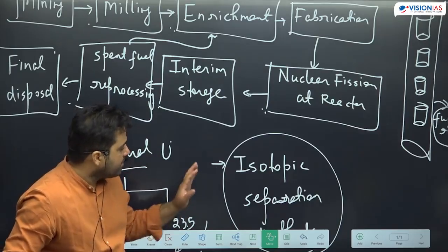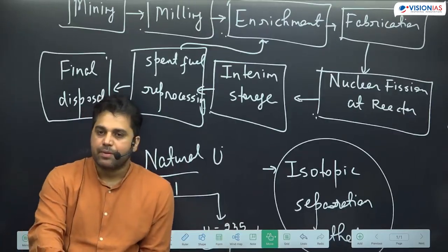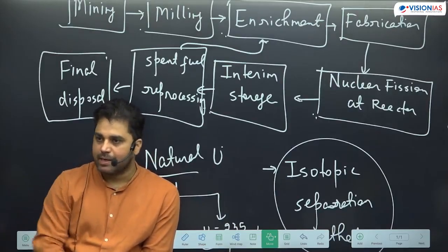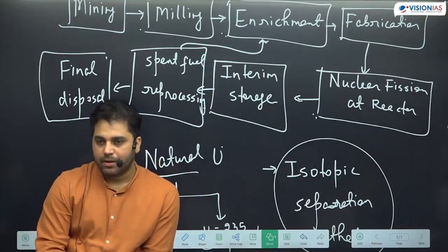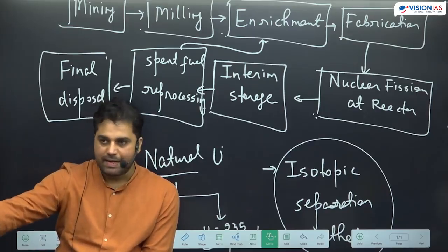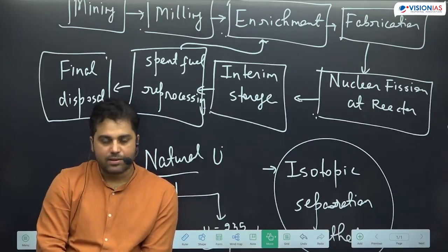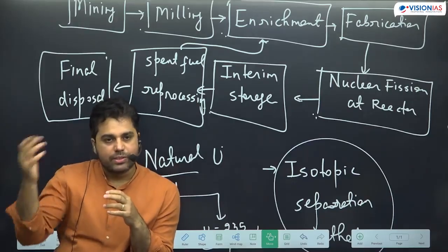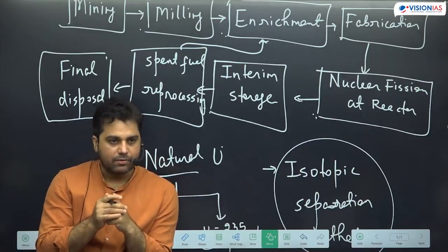Once nuclear fission stops and the assembly is exhausted, that assembly will be removed and kept in a deep pool of water. Within this reactor building, there will be a pool of water at least 20 to 25 feet deep. And we will keep all of that nuclear waste at the depth of this water. Now, water, it turns out, is an amazing thing. Water can absorb that dangerous radiation, and it will not allow that radiation to escape into the atmosphere. But we do not do that for a day or a week or a month. We do that for 3 to 4 years.